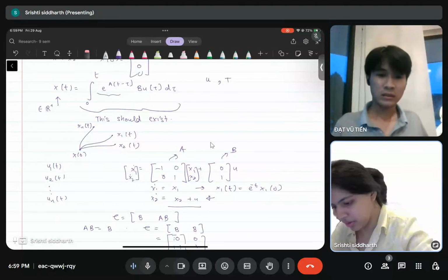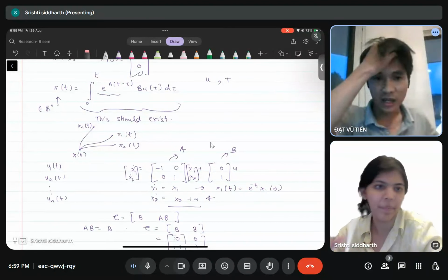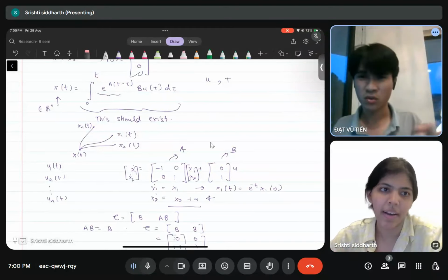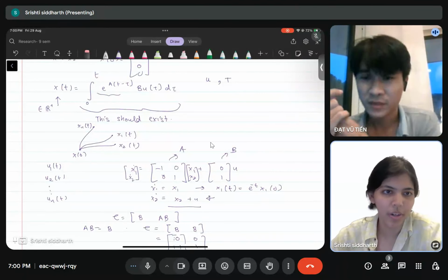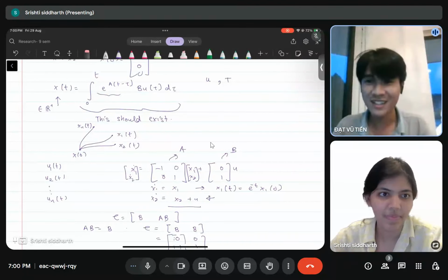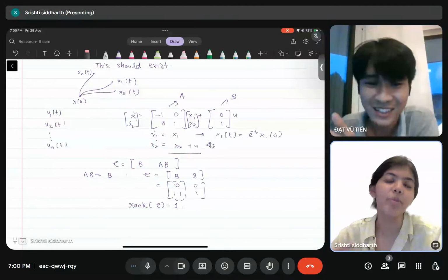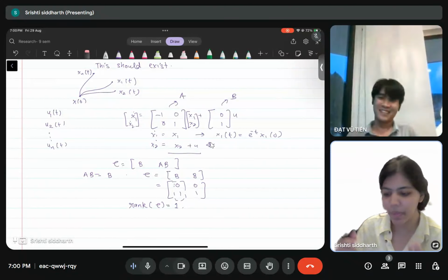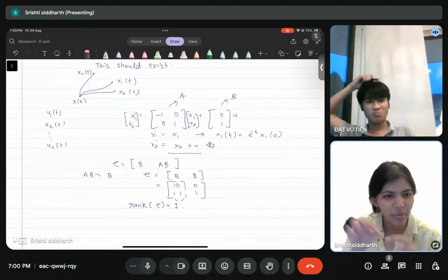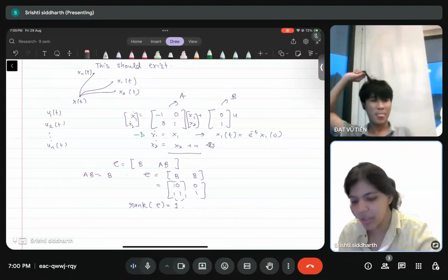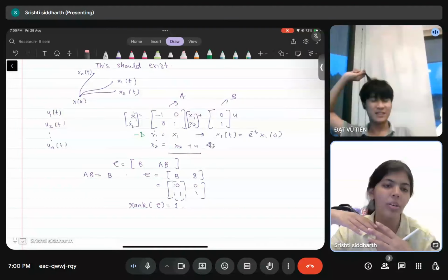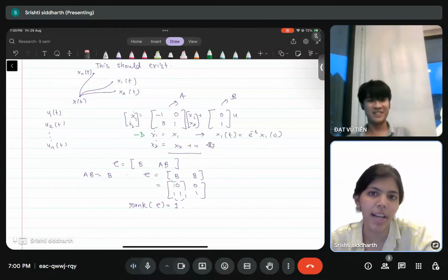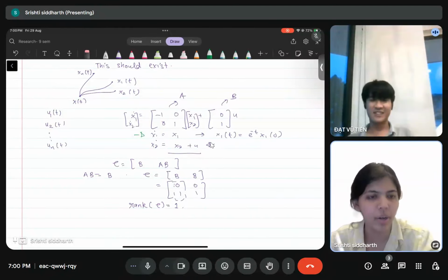Okay, so back to this. No, no, independent. This is not full or complete controllability. This is partial controllability. So partial controllability is the states which you can control, these are controllable, and which are not controllable, they should decay in time, right? Those states should not become unbounded. So that is partial. That is also known as stabilisability. So I think you will get to know more about it.